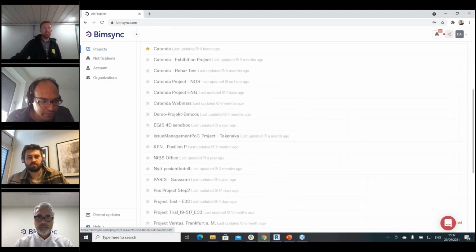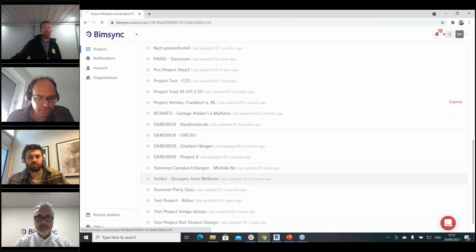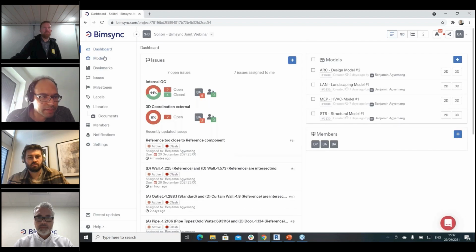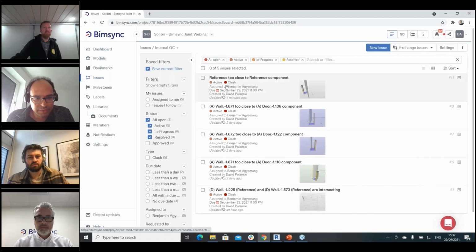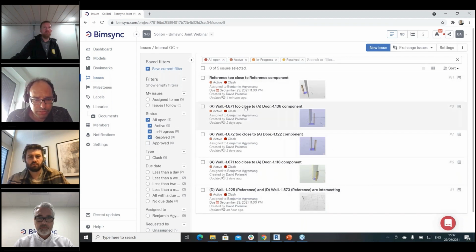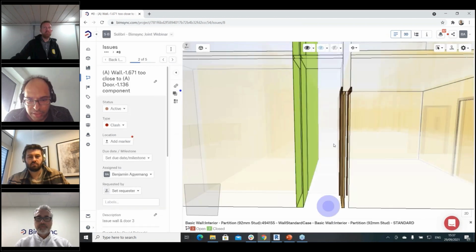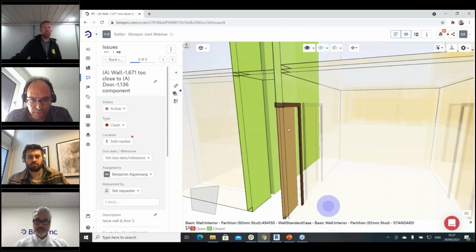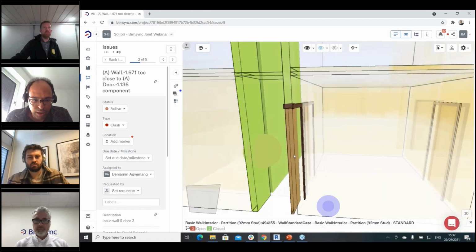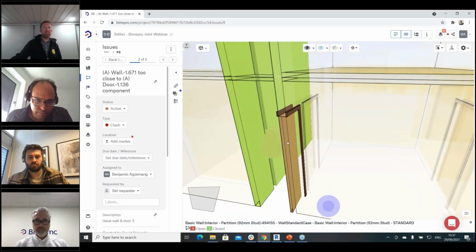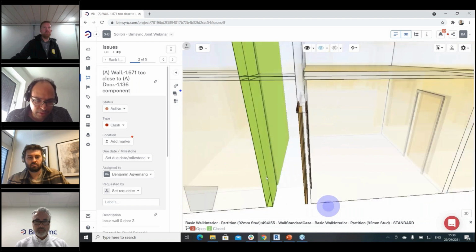All right, so we just have to get the project here, the Bimsync joint webinar. First of all, we can see here that all the issues that David saw on his side are here as well. So I could try these, oh, now it's working, and see, for example, that this door and this wall are colliding. It's colliding in the sense of a soft clash. So when this door opens, it's going to hit against the wall.